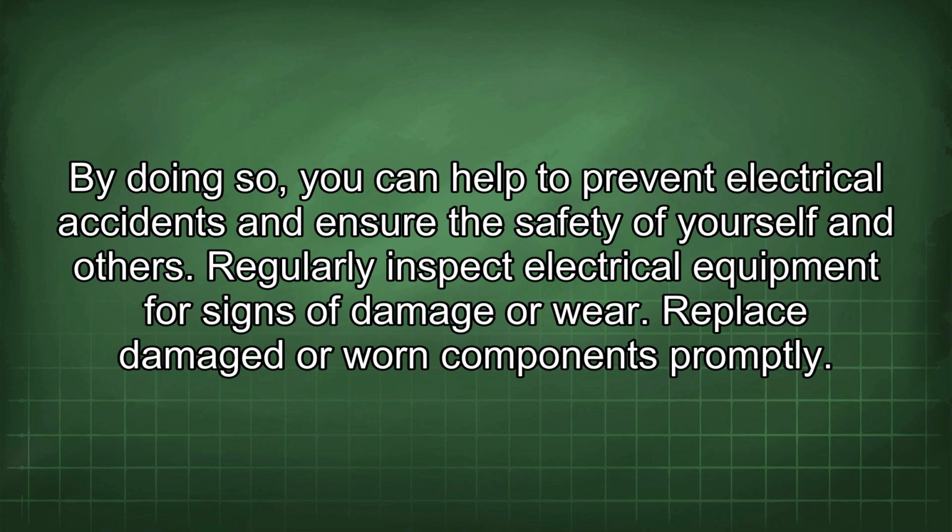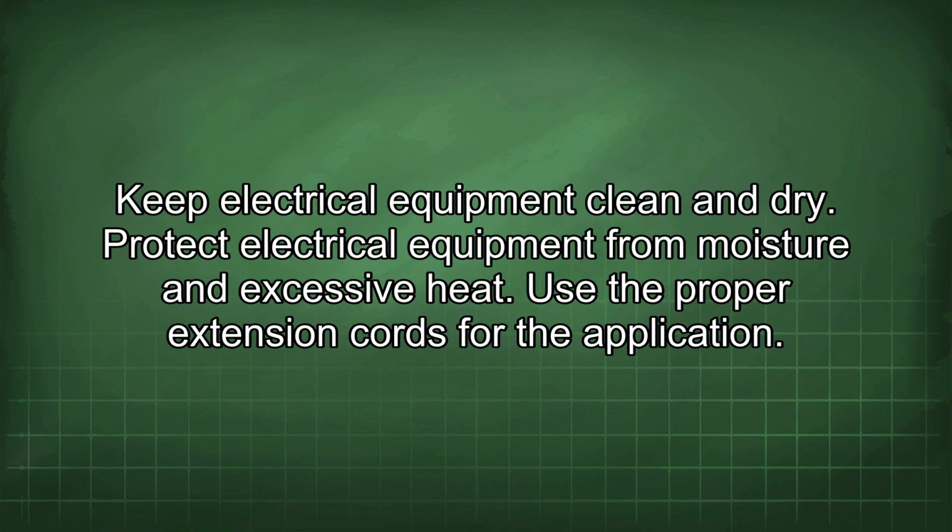Regularly inspect electrical equipment for signs of damage or wear. Replace damaged or worn components promptly. Keep electrical equipment clean and dry. Protect electrical equipment from moisture and excessive heat.